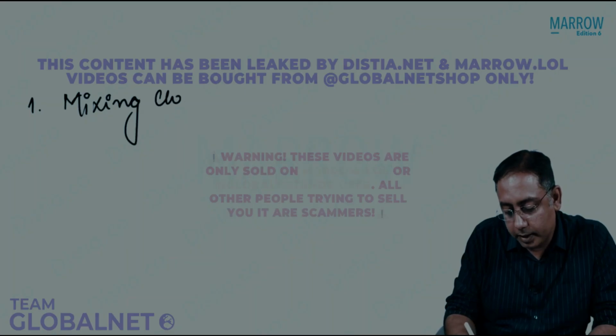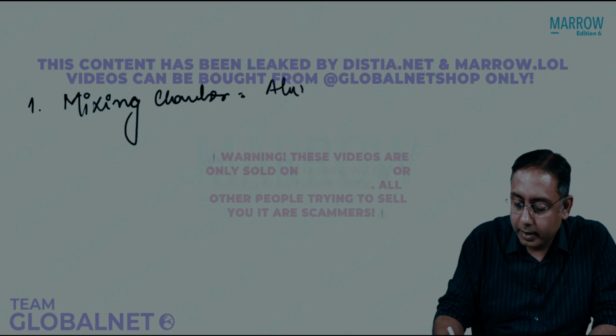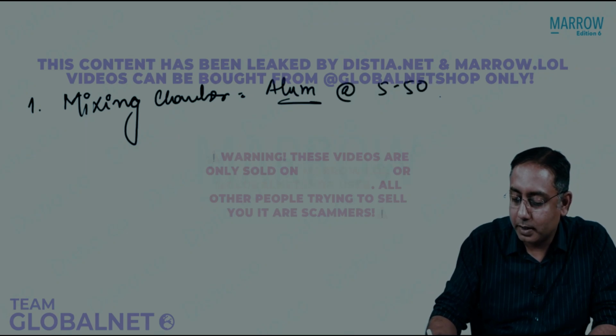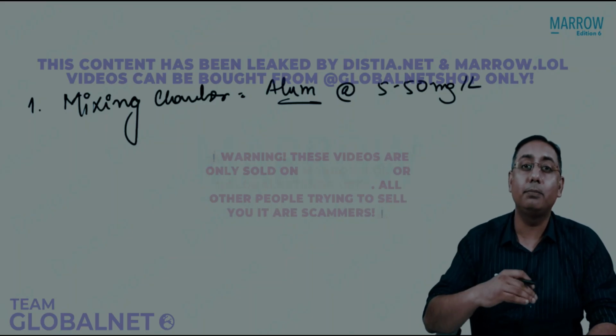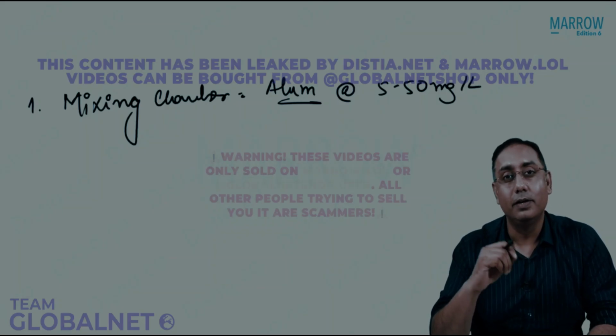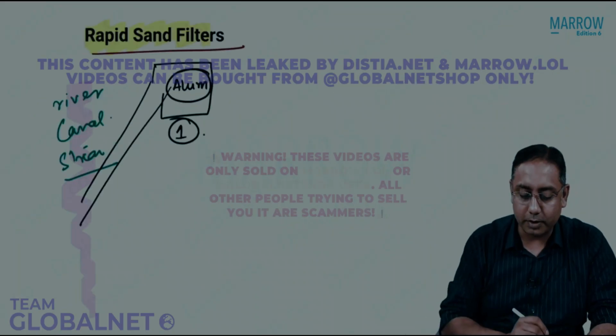In the mixing chamber, you are going to mix what? We are going to mix alum. Alum is mixed at the rate of 5 to 50 milligrams per liter of water, and of course it's a very big range. Alum can be as high as 100 milligrams per liter. We can mix alum, so it depends on the contamination level of water.